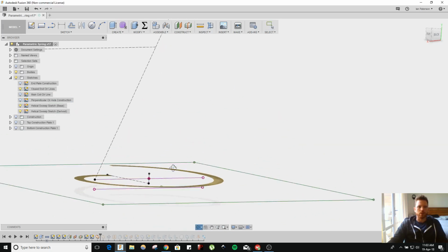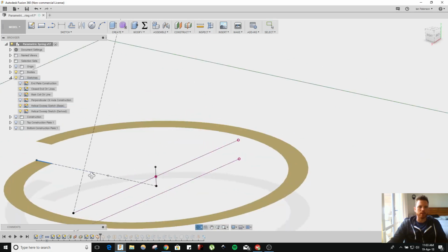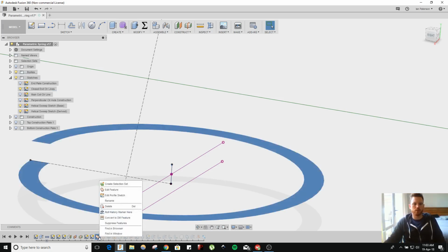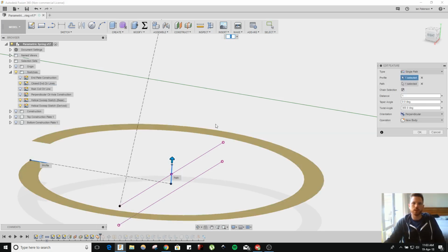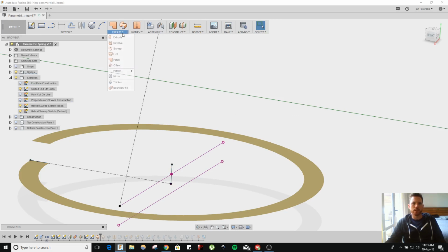Here we go. That line segment there is drawn on the plane that sits at the end of this little center line, and then we use this coil. Or what's this called? Let me jump in the patchwork space and see. It is a sweep. So it's a sweep of a line, and that creates this 2D ribbon geometry.